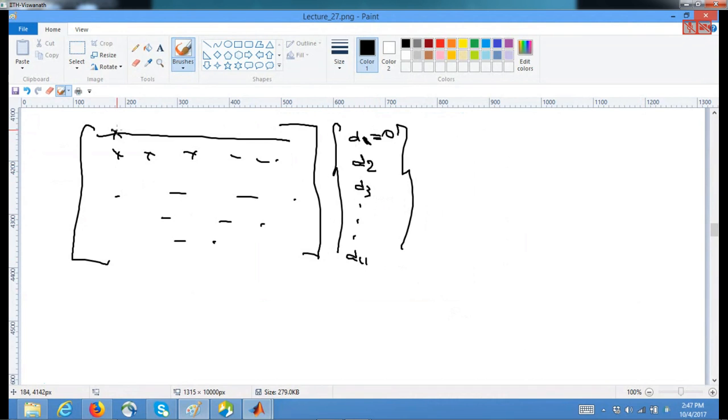What he does is he takes the first row for which the displacement is specified, and replaces everything with zeros, except the first one, which he puts as 1. He will put it as 1 and all other things as zeros. If the constrained degree of freedom is in the first position, you put the 1 there. If it is in the fifth position, you put 1 there, and the rest of the things are 0.